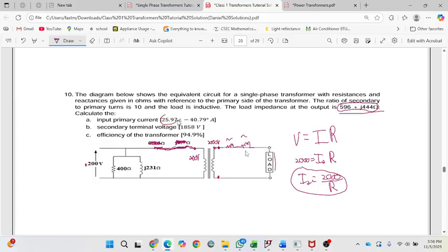So you can get this, which is the magnitude, that is okay. You can get this, which is the angle from here. Normally they'll give it here as a power factor, or sometimes they could give it here as a complex form. If you have a complex form, you could just do your normal tricks to calculate your angle from that, and the angle obviously will be positive because you can't have a negative load. But you just have to know that when you're actually doing the angle itself, if they say it's inductive, the current angle will be negative.